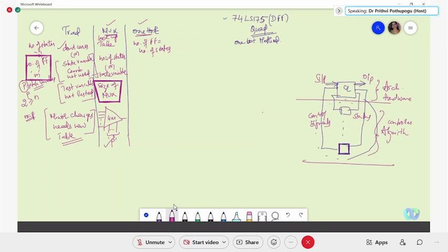Here if you had 4 states, 2 flip-flops are enough. But here 4 states means 4 D flip-flops are needed. So the more the number of states, the more the number of flip-flops, and maybe that increases the complexity and the cost also. And what is the disadvantage we were having in this one hot? First is the initial state. It should be by default, maybe we name this as PQRS or something. Say state 1 is the first state, it should start from that state, the initial state.